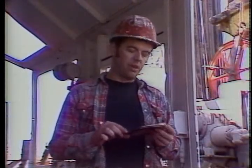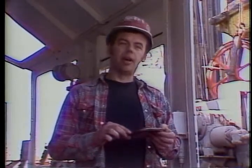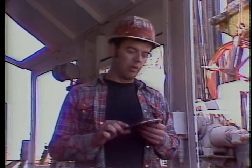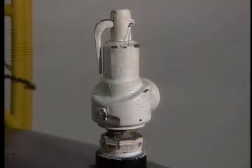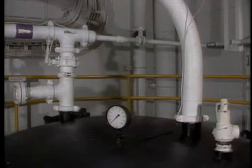So great care should be taken when allowing the flow of air to enter the P tank, for too much volume will cause this disc to rupture, and also over a prolonged period of time, too much pressure will result in the same. Some rigs use pressure relief cocks, but both serve the same purpose. They're safety devices that are on most of our systems to keep you from blowing the system up.